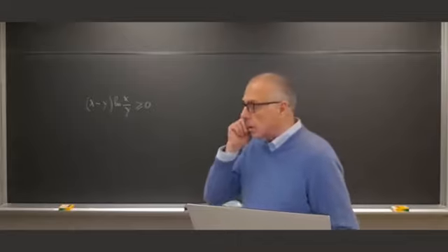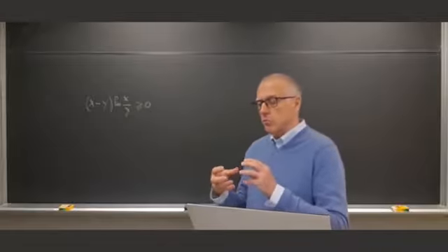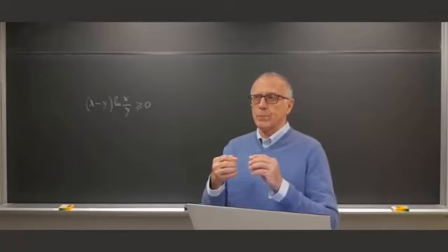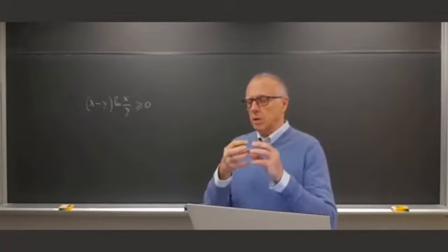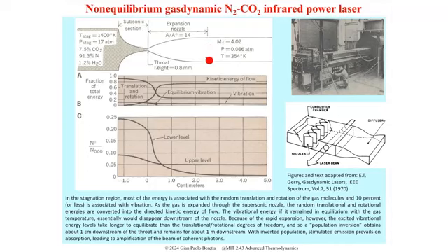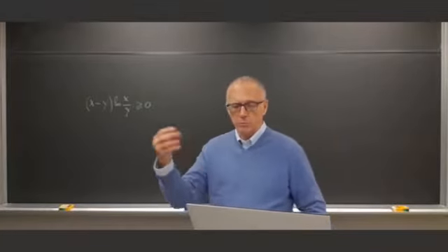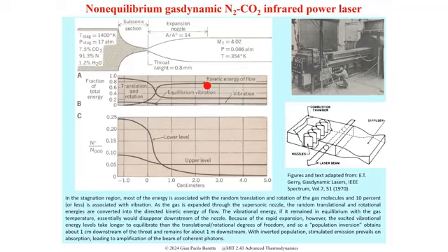And if the collision mechanisms were very effective, as soon as the translational degree of freedom cooled down because of the expansion, you see the temperature goes from high to low. So that means the thermal kinetic energy cools down, it transforms into flow kinetic energy. You can see that here. This is the flow kinetic energy. It goes up, and this is the thermal kinetic energy that goes down.